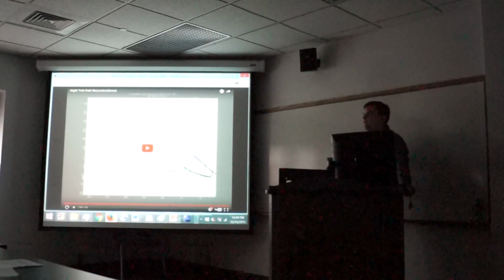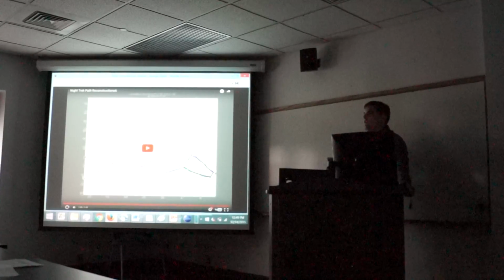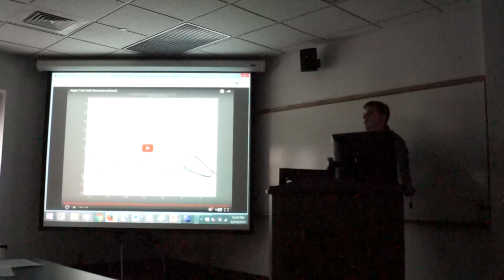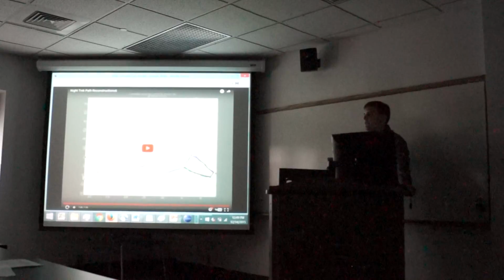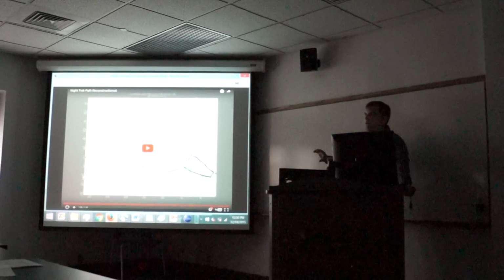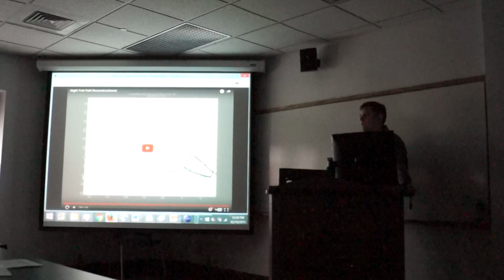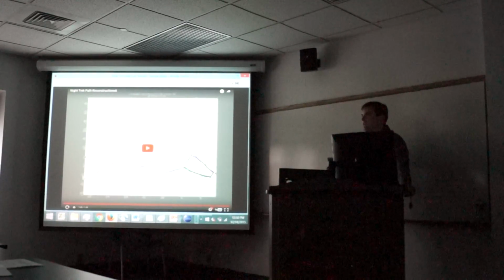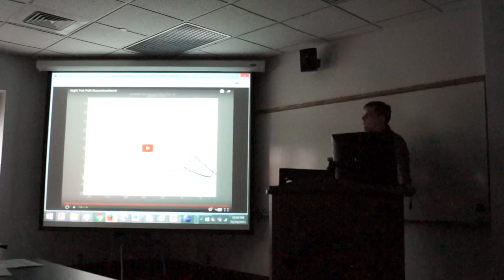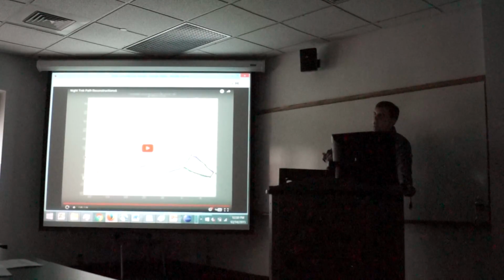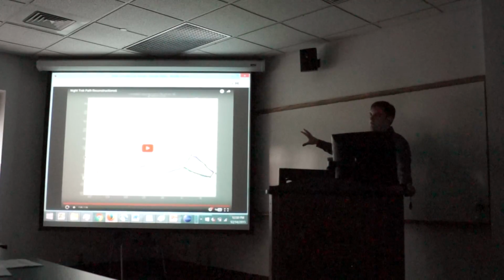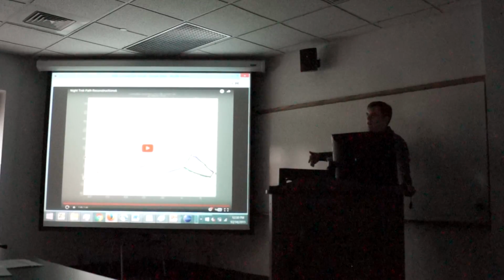In this case, we were able to tune the exposure, the brightness, intensity, and the area size threshold for the light at the beginning of the test before we started recording data. So we were able to do a pre-calibration before the run to make sure that when the artificial sun was occluded, we weren't going to pick up the other lights. So that was the intensity cutoff.